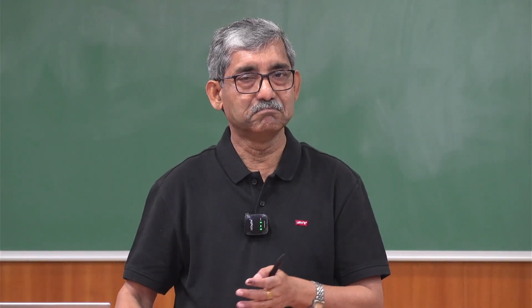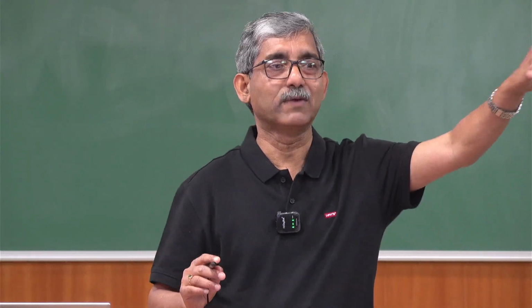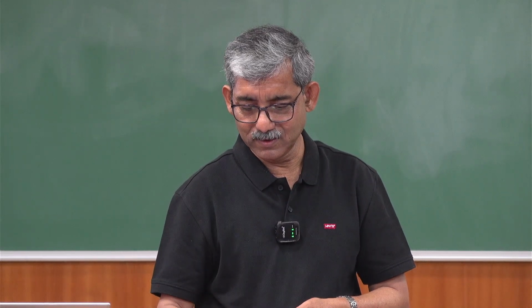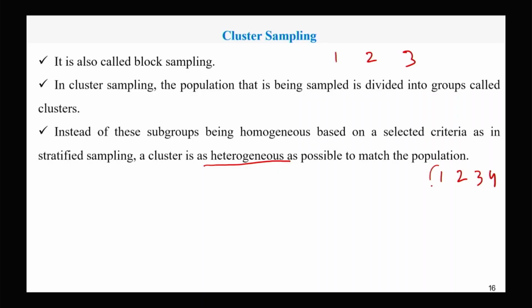Similarly, suppose we have 4 different ring frames. Ring frames 1 and 2 don't create any problem. They are new. From our basic experience, we know that 1 and 2 are running perfectly. 3 and 4 sometimes create problems. So in that case, the sampling is taken from 3 and 4 to check whether count variation is there. So this is how we are clustering. Or maybe from 4 different makes, we are taking a specimen from only 1 make.